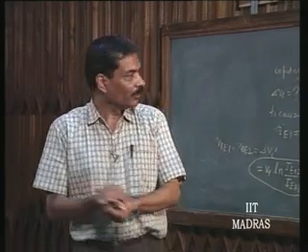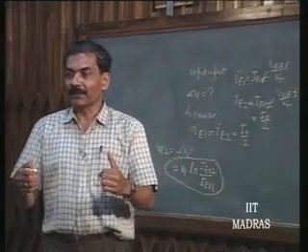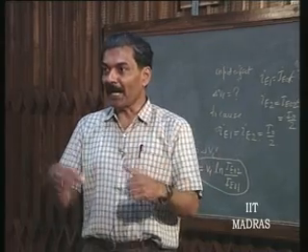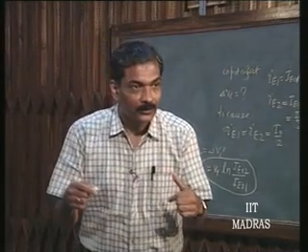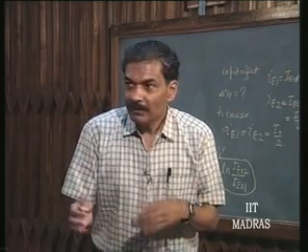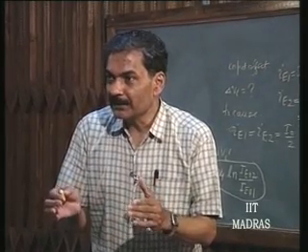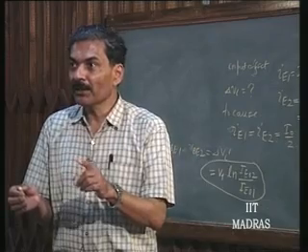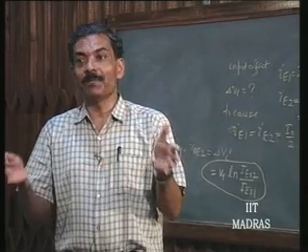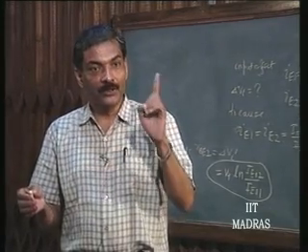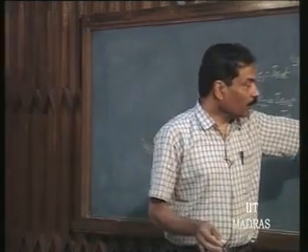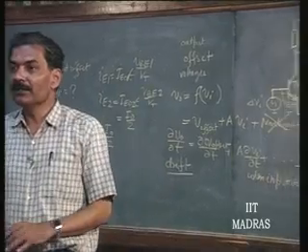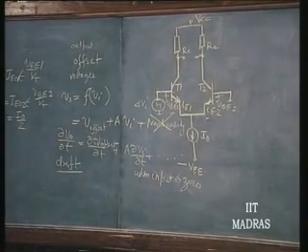If we use one pair, this is the input offset. If we use two pairs, each of the pairs will result in 1 to 2 millivolts of uncertainty. So uncertainty will keep on multiplying with the number of pairs. So please remember this in your design, that for whatever reason, if you increase more pairs, what are these called? Darlington pairs.